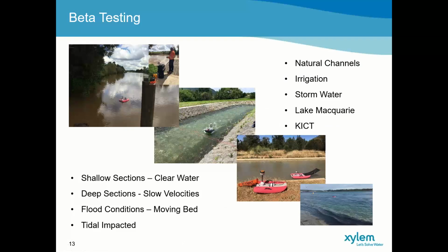So, beta testing. I'm not sure if you had a chance to look at the webinars and papers provided by SonTek, but there was significant testing done across the world and in various different channel conditions and sites. In Australia, we've done the same. This photograph here shows a measurement done in the Hunter River that is tidal impacted. So you have soft sediment deposition in the channel itself, which was a great test bed to verify bottom tracking.